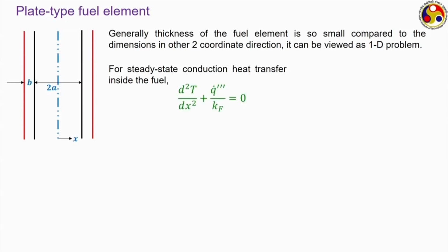So, under steady state the heat transfer in the fuel can be written following the Cartesian coordinate system. Just to repeat, conduction is the only mechanism that is happening inside the fuel, this being a solid, and now the generalized heat conduction equation in 3D Cartesian coordinates can be written like this.